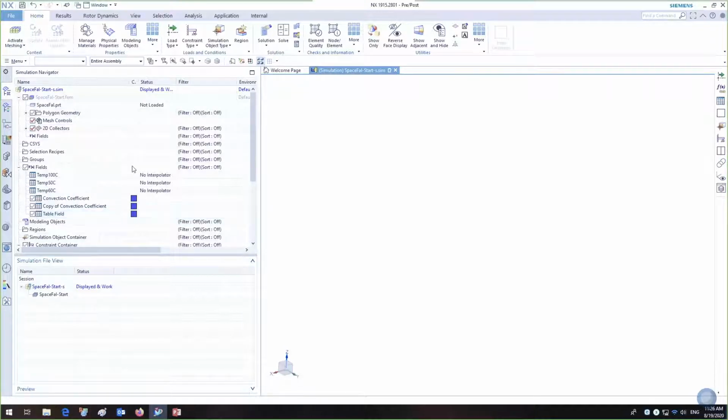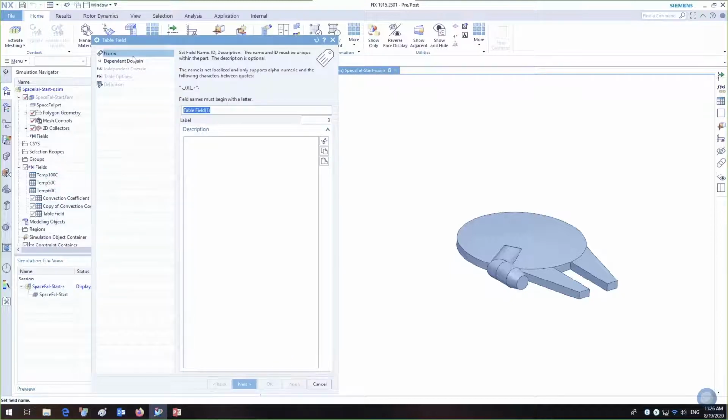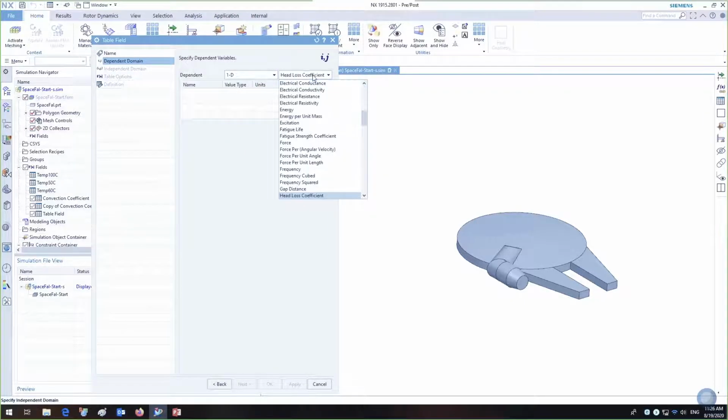Now, that was a heat flux that was dependent on Cartesian and temperatures of the surface. Now, we might have a slightly different relationship between our heat flux and our variables. So instead of doing a Cartesian and temperature dependent heat flux, we have a heat flux that is actually dependent on the surface temperature, but also the time of our simulation.